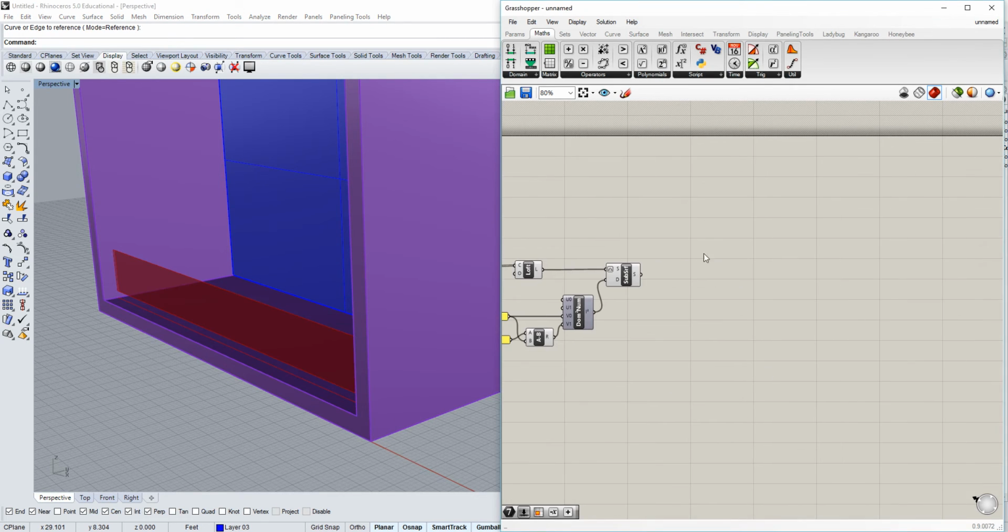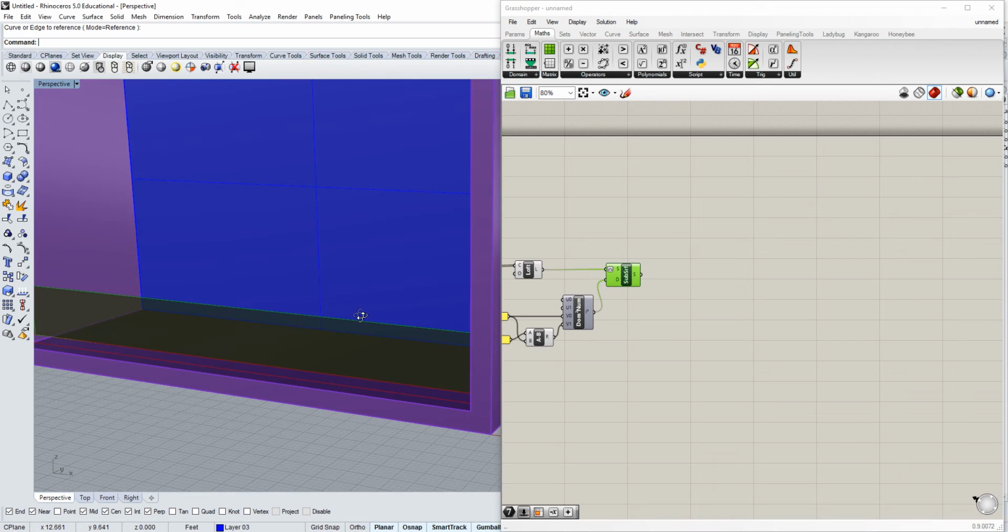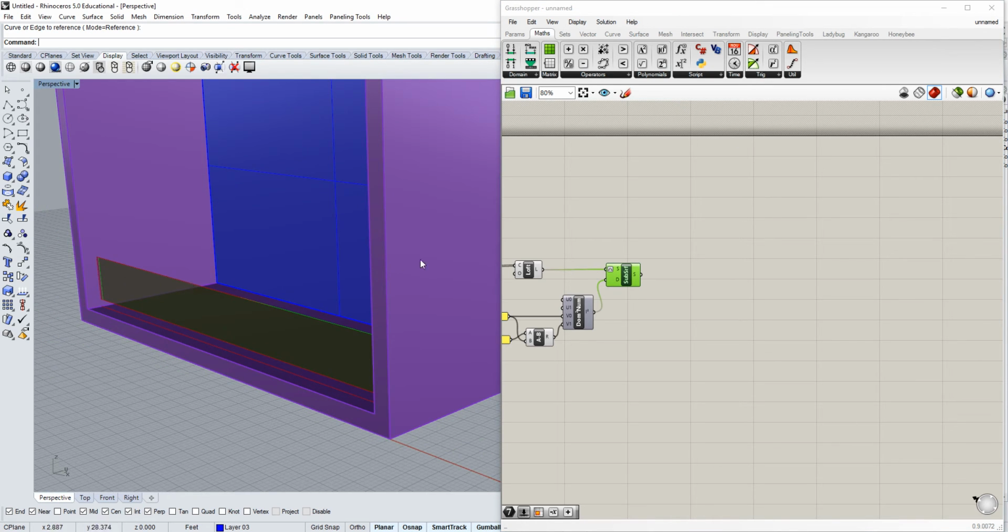And we had a number of discussions about the different kinds of rotations we can do. So I'm going to take this surface that I just created and tilt it outwards before I do my subdivision. The truth is, you could really do the tilt part later. However, once you subdivide the geometry, then you have multiple geometrical lists that you have to tilt out. So you'll have the individual panels, the edges, and the pipes that you create around them. But now, since we just have one surface, it's smarter to do it here.